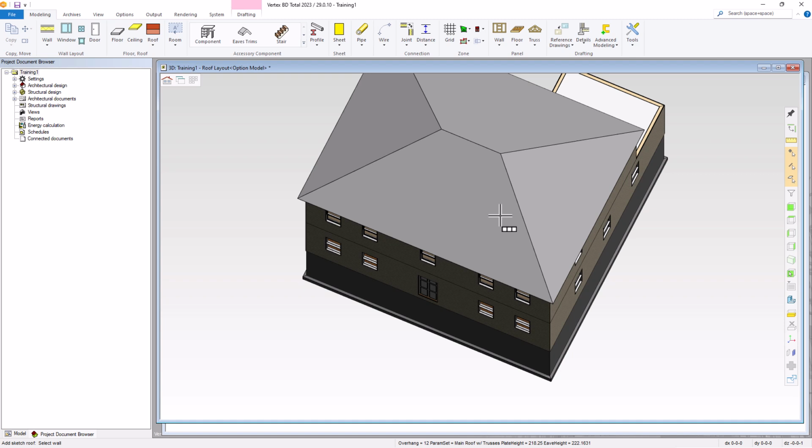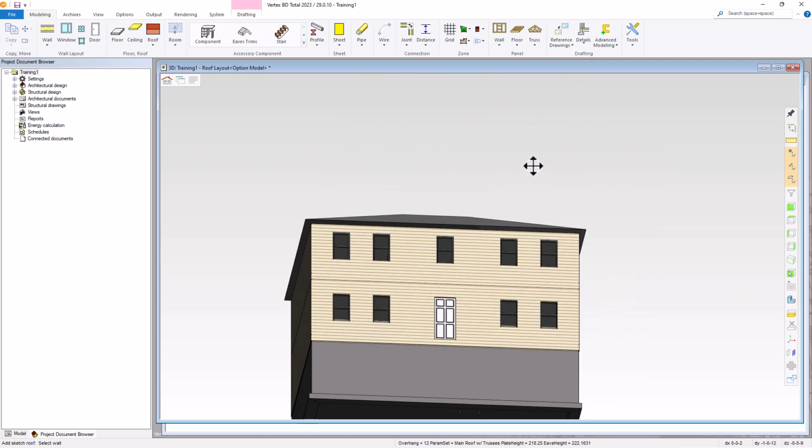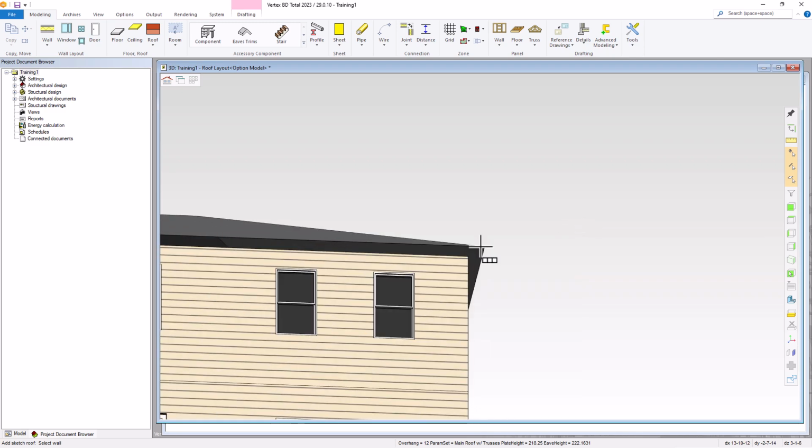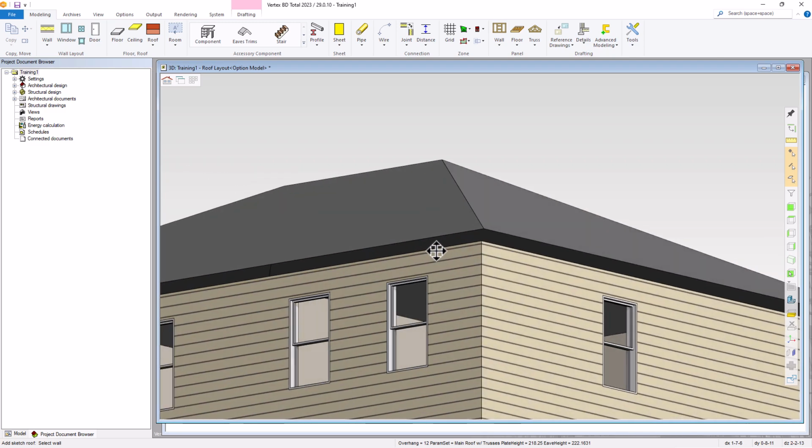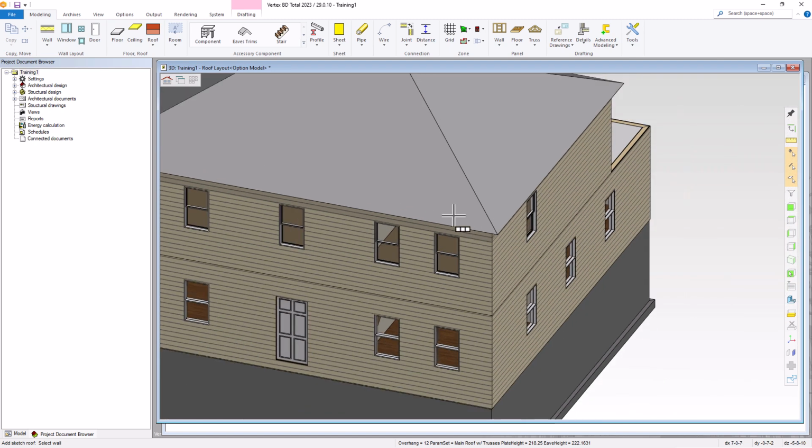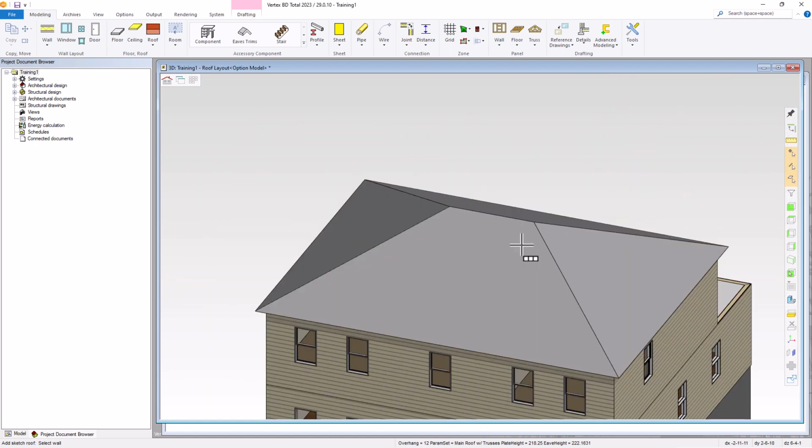This is called a sketch roof. At this stage, it is a rough outline of the roof made up of planes. Other adjustments can be made before converting it to a roof. Let's zoom back out. Before we convert the surfaces to a roof model, we can make any changes to the roof sketch, such as eave overhangs, change the roof pitch, the gable type. These changes can be made in the 2D or in the 3D view.